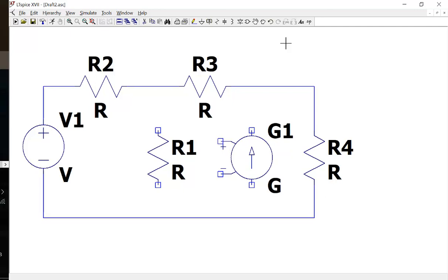So for that type of project, I'm designing a high voltage switch because I still don't know how to do it. I have never done that before. So I have to test a lot of ideas really quickly. LTSPICE is the only option I can use. I have to build all the transistor circuit in there and test if I can get that high voltage oscillated.